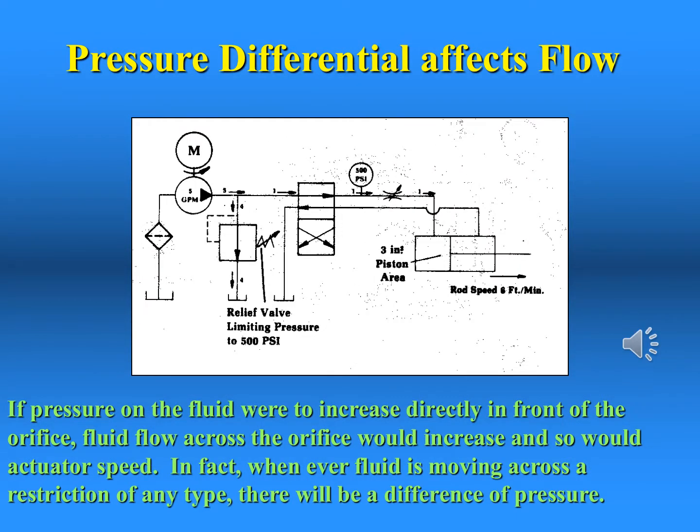This slide shows what happens to pressure and flow upstream when there is an increase of resistance. The needle valve and load affect the reading on the upstream pressure gauge. If the needle valve's opening is reduced further, it stands to reason that the pressure at this point will increase and flow across the needle valve will decrease. As the opening of the needle valve is reduced further, the flow reduces in direct proportion. This is very easy to demonstrate on the training equipment.